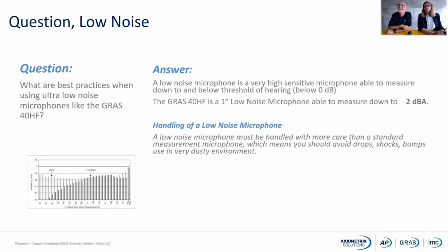And if you misalign it, then the microphone will change its sensitivity, and it will also change its frequency response. If its sensitivity has changed, then maybe you can't measure the low levels as you would like to do with the low noise microphone. So therefore, you must handle it with more care than you handle a standard measurement microphone.